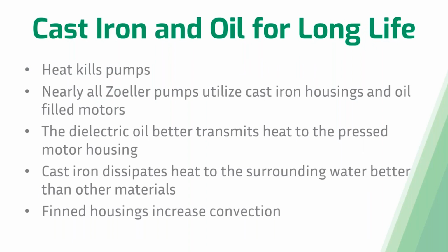So now let's move on to cast iron and oil inside of our pumps. The number one killer of pumps is heat. So nearly all Zoeller pumps utilize cast iron housings and oil-filled motors to dissipate that heat from the motor to the surrounding water. The dielectric oil inside of that motor housing transmits heat to that pressed motor housing. And because that motor housing is made of cast iron, that cast iron dissipates that heat to the surrounding water. And this is typically better than other materials that you may find with pump builds.